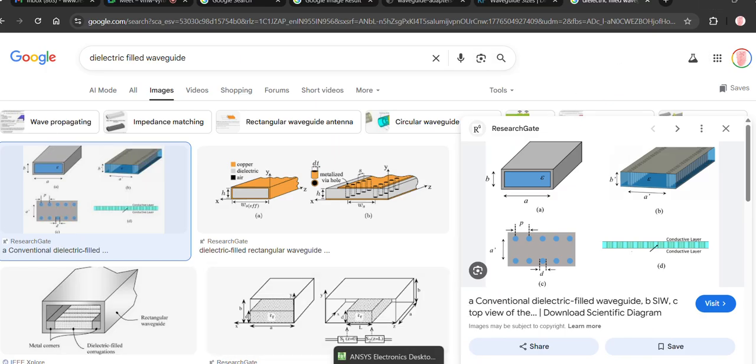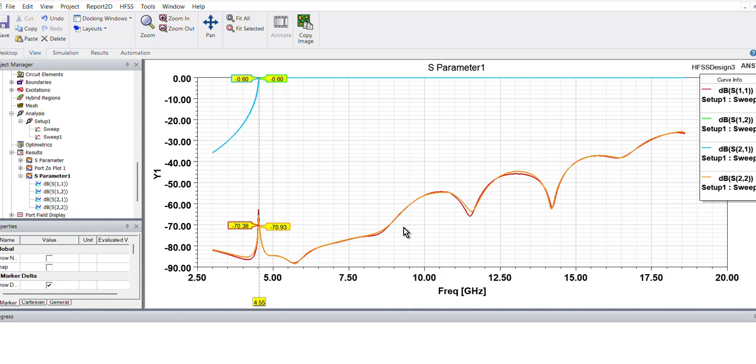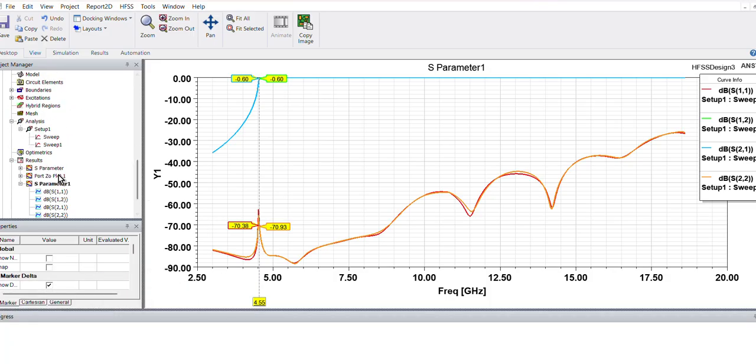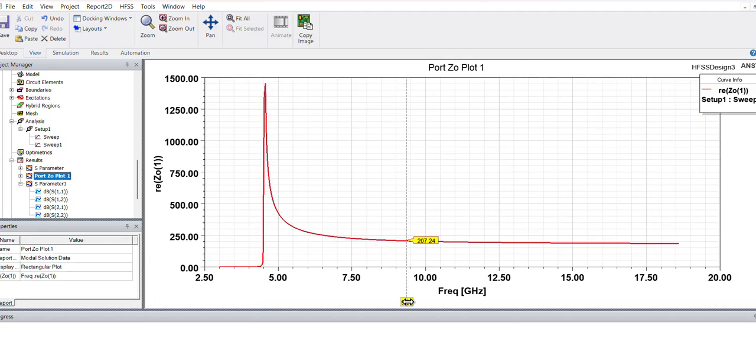Next, we shall do another experiment. Now our design has shifted. To make it the same waveguide, we again need to follow that 25% rule, that my operating frequency should start at 1.25 times the cutoff frequency. Actually, in this one we can use it. Again, whether that is correct, let us see here.